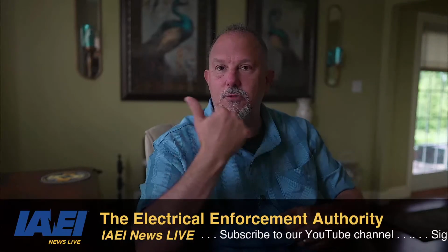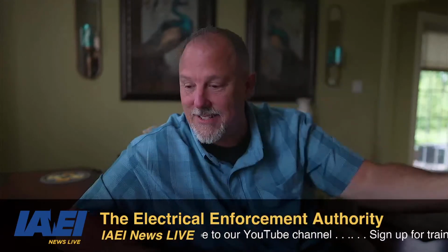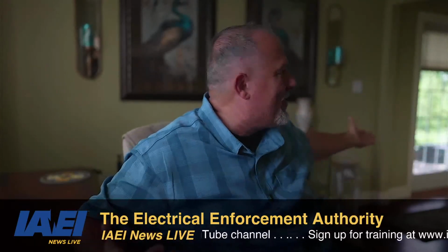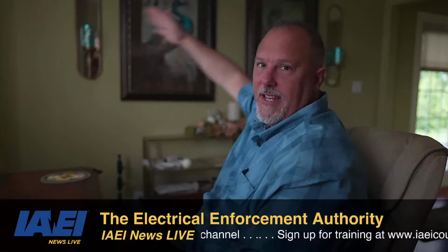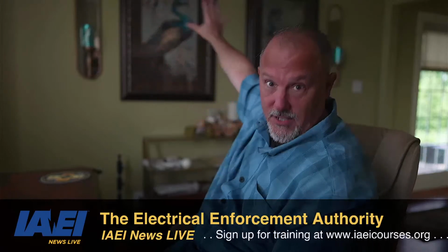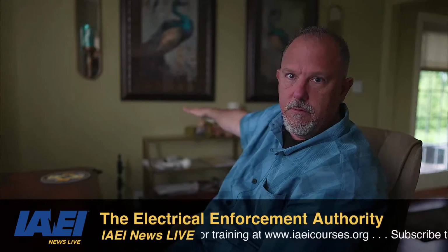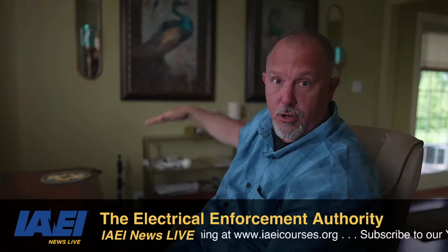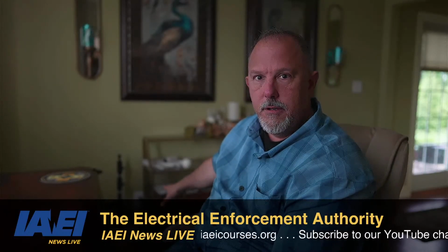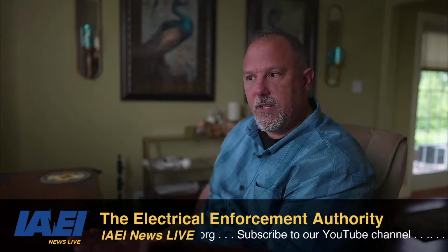To me, okay, so Michael says, no, I disagree. Felix says, yes. And Steve Froming is like, what room are we in? We're in my office here, and I have bookcases on this wall. Imagine, if you would, a world of bookcases on this wall. And I've got 4 foot of a work surface. I would need a receptacle on top to serve the work surface. I'd also need a receptacle on the bottom, underneath, for a general purpose receptacle to meet the requirements in 210.52(A).